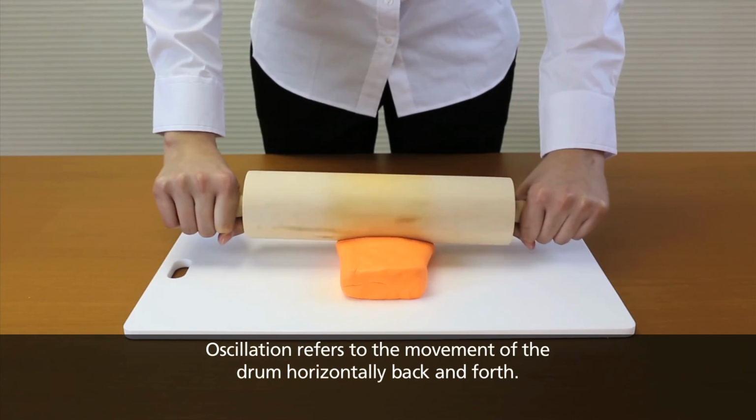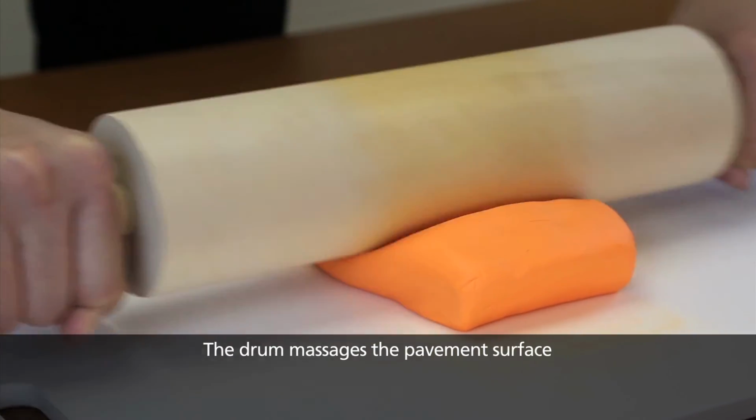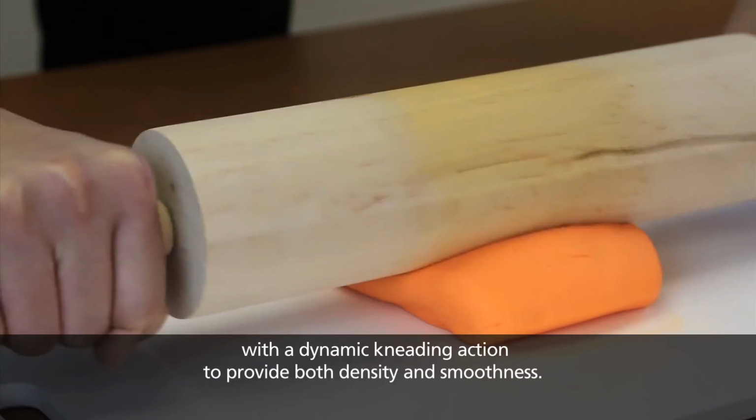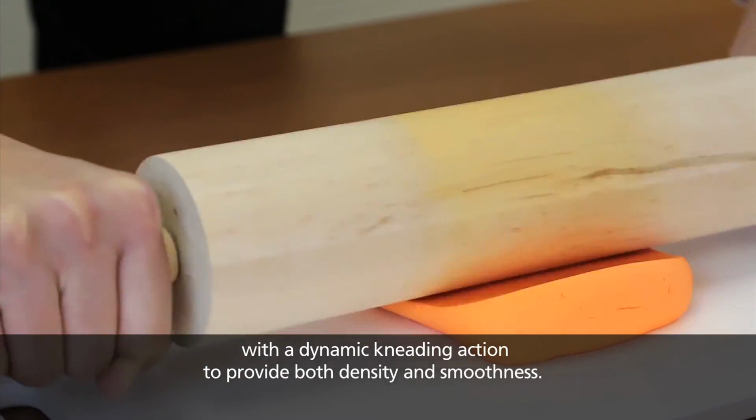Oscillation refers to the movement of the drum horizontally back and forth. The drum massages the pavement surface with a dynamic kneading action to provide both density and smoothness.